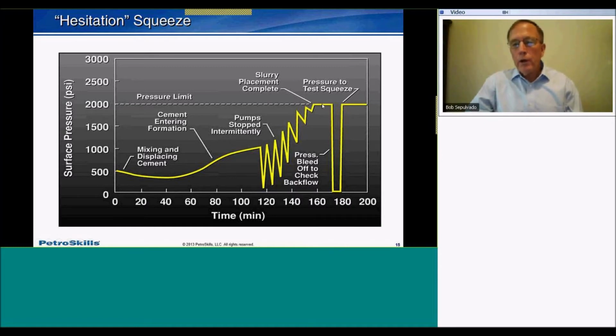So we hold it for a few minutes to make sure it will hold. Then we release the pressure into the displacement tanks on the cementing unit, and we look at the volume coming back. All we're interested in is the volume of fluid coming back into the displacement tank. Basically, it took the charge of the system to the pressure. You know, that might be a barrel, a little bit over. That's all we want to see.